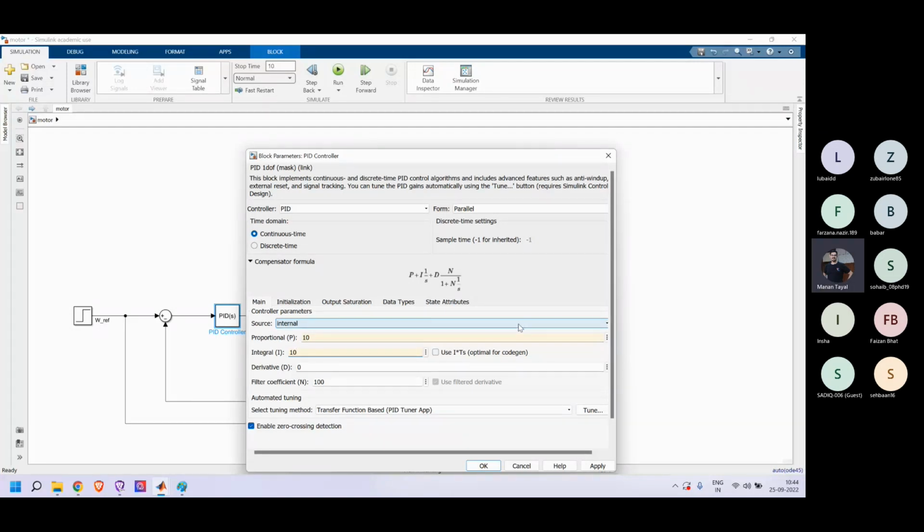If there is a sharp change in slopes, this term will shoot. If the frequency is very high, this derivative term will shoot very high, and we want to avoid very high frequency signals, so we put a filter, a first order filter.